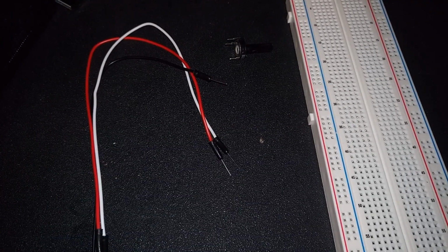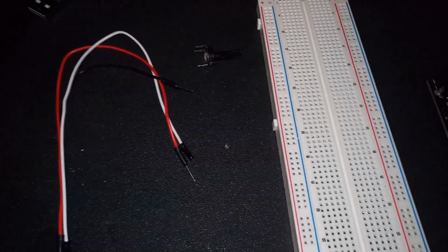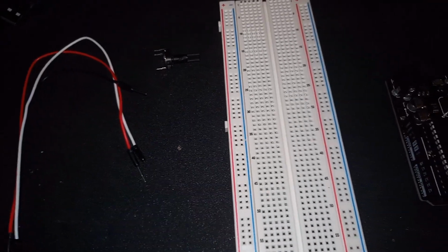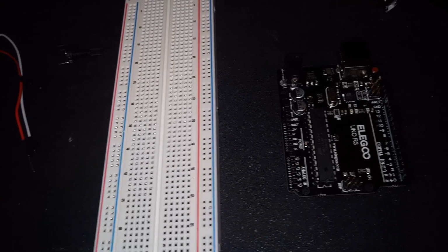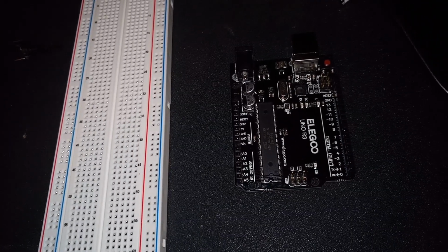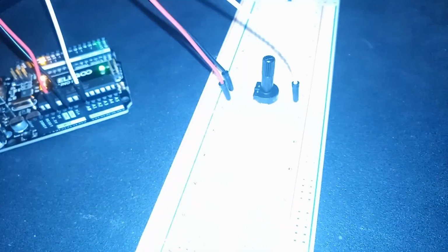This example shows you how to read an analog input on analog pin 0, convert the values from analogRead into voltage, and print it out to the serial monitor of the Arduino software IDE. Connect the 3 wires from the potentiometer to your board.